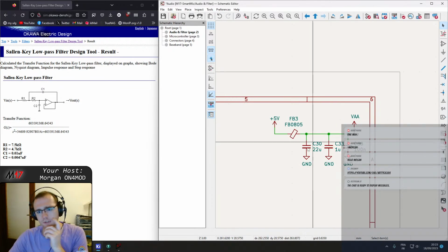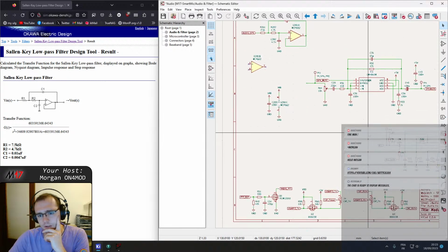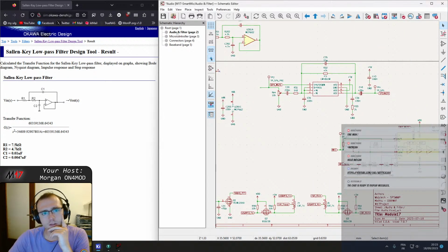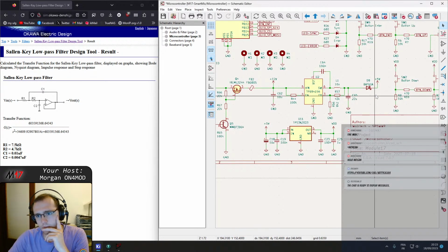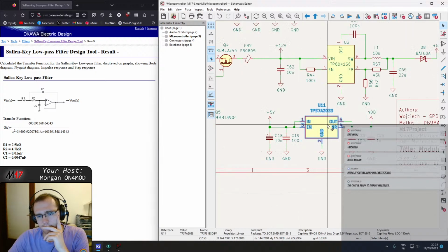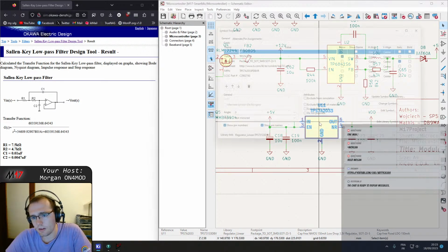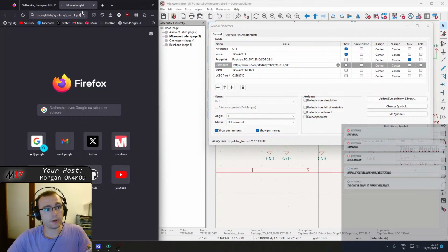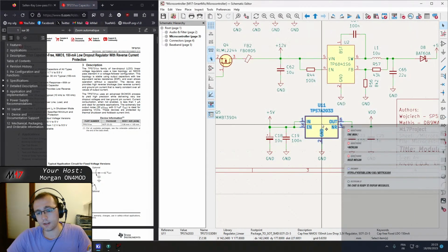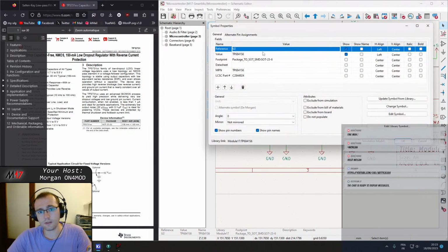Okay, yeah, I would have used 3 volts, maybe. How is the 3 volts generated? It's an LDO, sorry, not an LNA, an LDO from the 5 volts. So this most probably has less noise. Let's just check quickly. So this, and also we need to see how this one works.